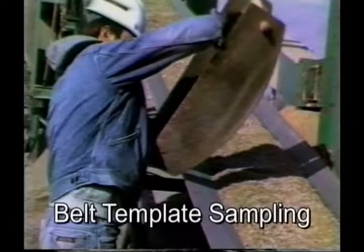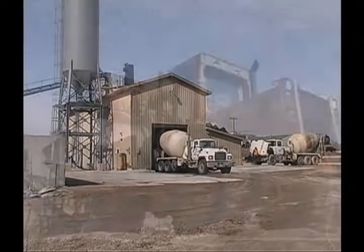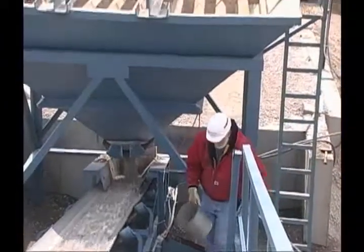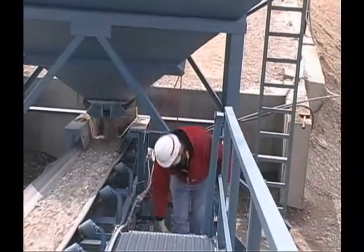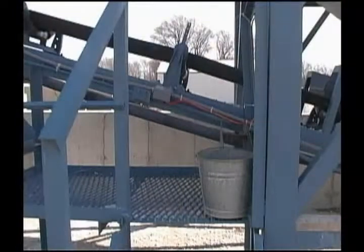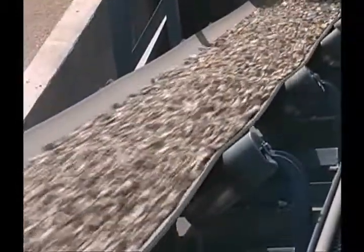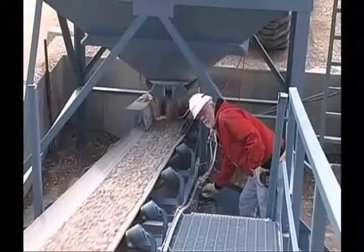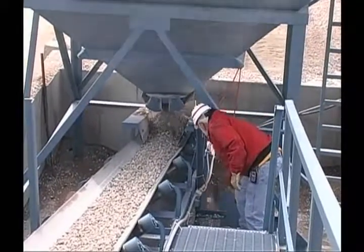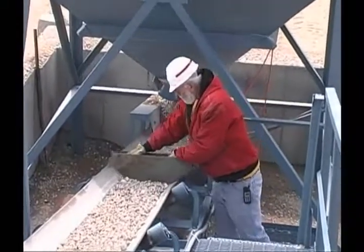The belt template method is most common in paving, ready-mix, and asphalt operations, and is usually the hardest to perform. Difficulty arises in finding a good location to get a sample. The belt is to be equipped with a shut-off switch at the sample location to be operated by the sampler. With the belt at full capacity, stop the belt and with a template that conforms to the shape of the belt, place it down on the belt, being sure to cut the entire depth of material.